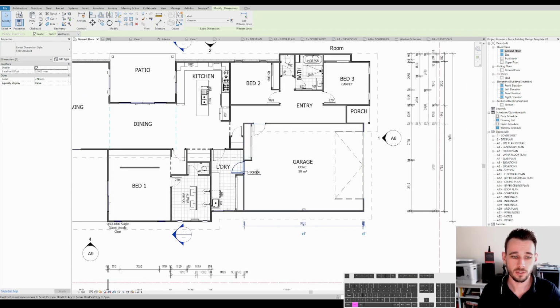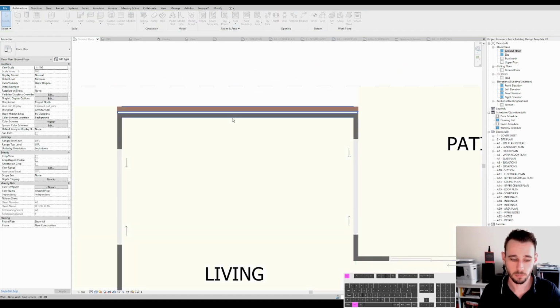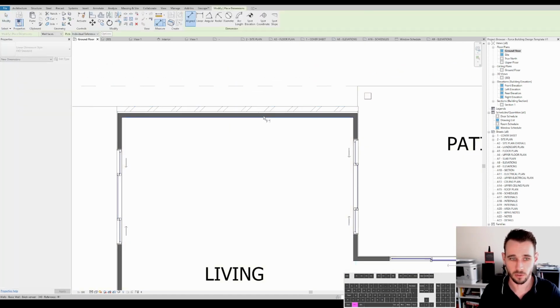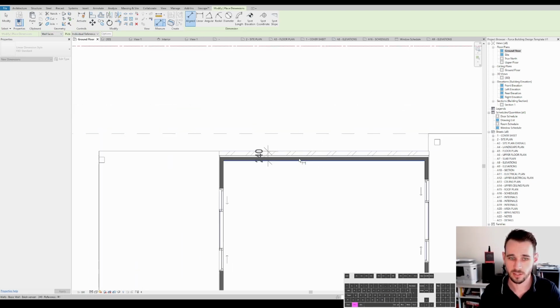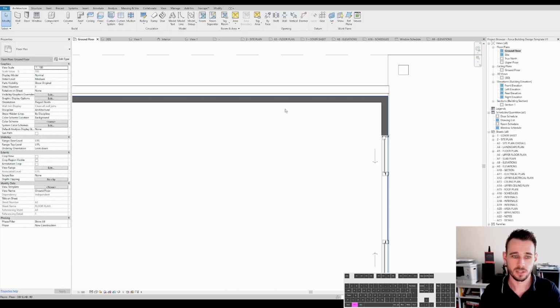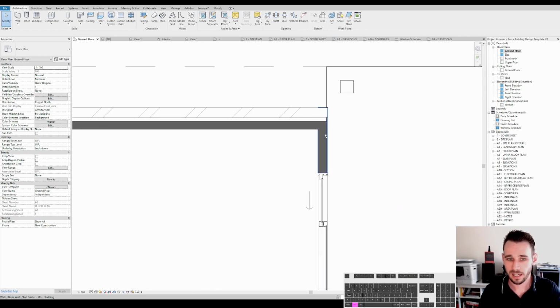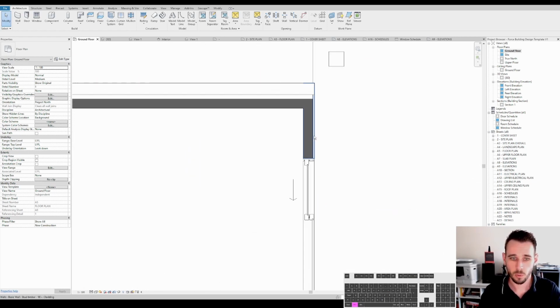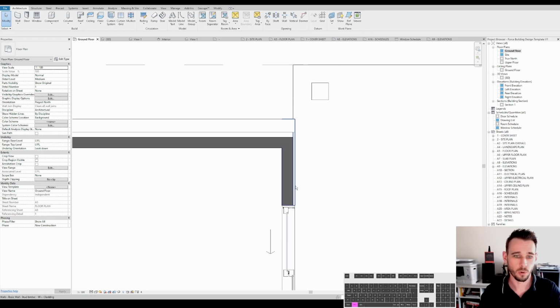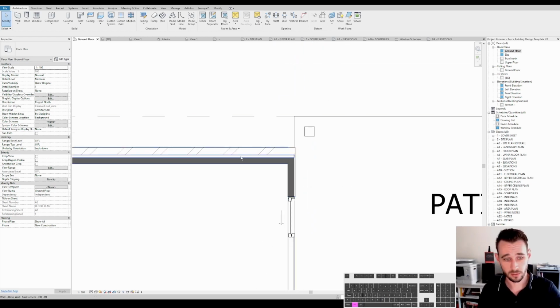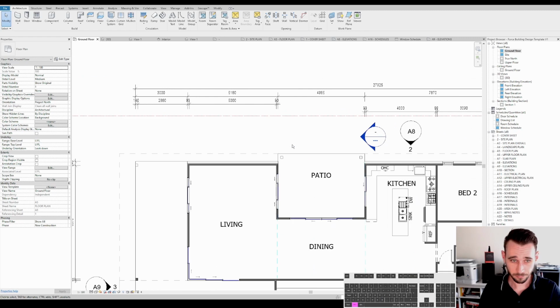Now what I'm saying there, it doesn't apply to brick. Brick's different. Brick's a standard thing. You get a brick. A brick is a unit. There's not much variance in the actual width of brick. So this is going to be a 240 wall because it's 90mm of stud and then cavity and then brickwork. Brickwork is just kind of the same. Lightweight cladding, like we don't know if that's going to be FC or weatherboards or blueboard or whatever. It could be anything. 240 is good. 105 is bad.